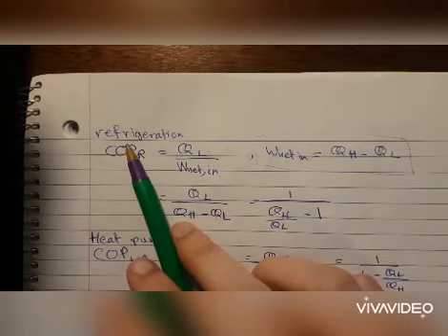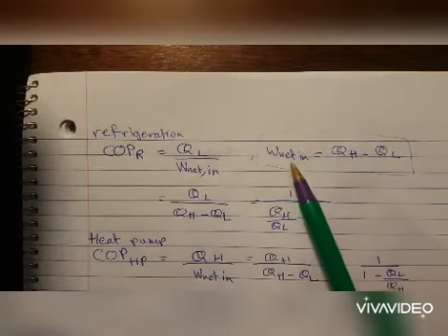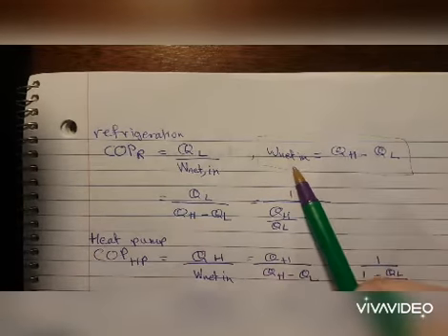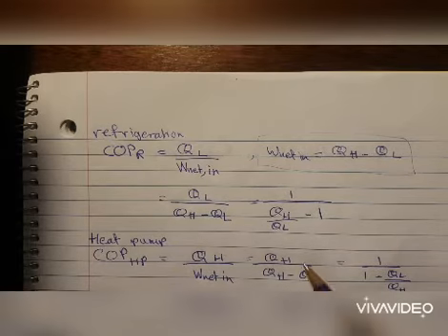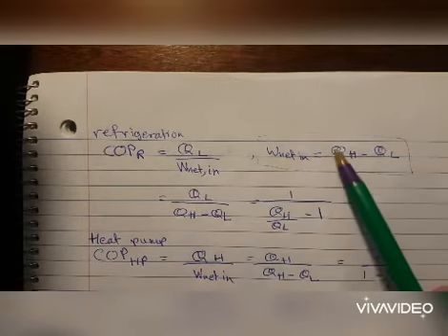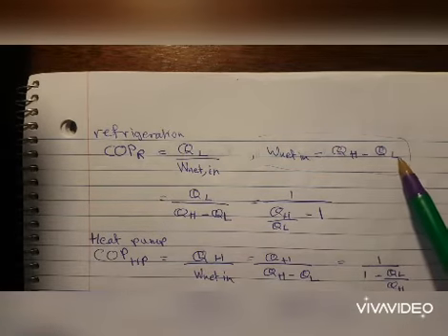But in a refrigeration, we are giving work into the system to get heat transfer being done. So our refrigerators in our houses take electricity as work in so that they can keep our things inside cold. The electricity provides work in to cause heat transfer from inside the refrigerator to outside, making the insides of the refrigerator cold. So we have work in, and then there's QH to a high temperature reservoir minus QL from a low temperature reservoir.